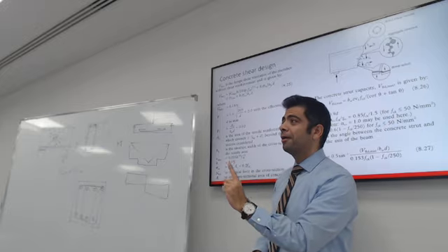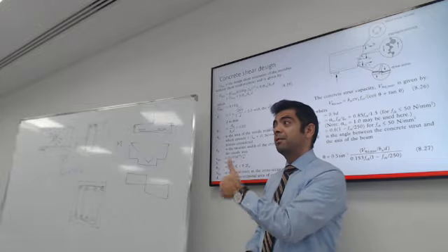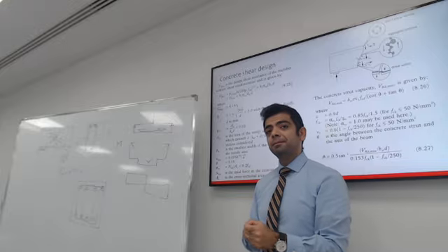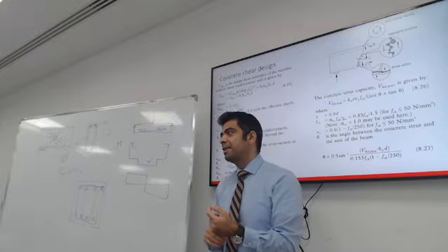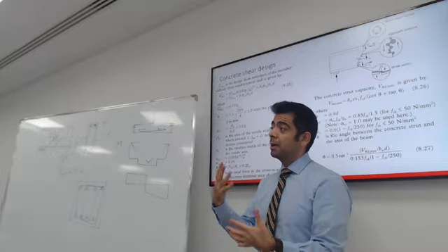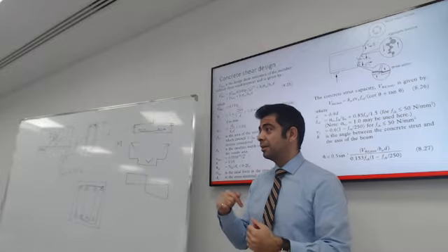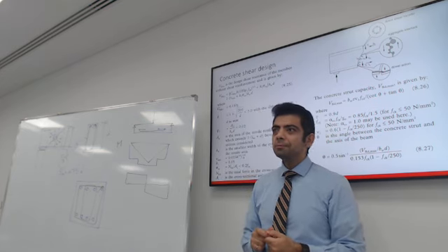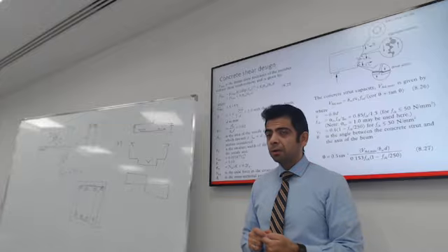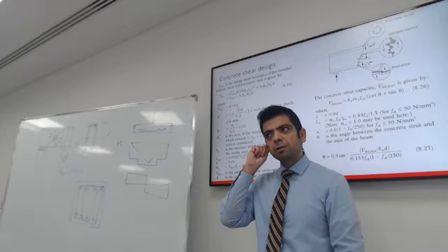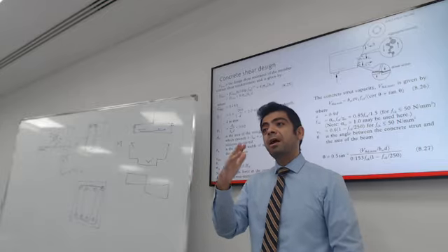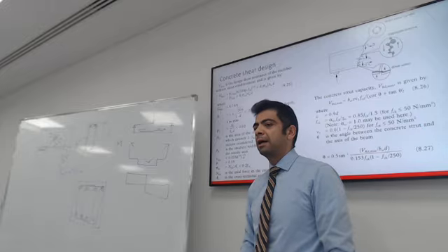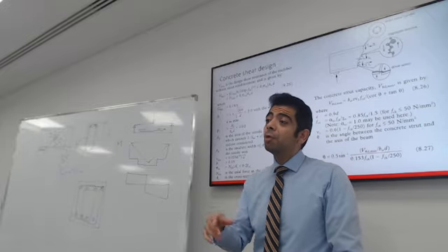There is one more element that could enhance or reduce the concrete shear strength. I'm curious if you can think of it. There is one more element that can increase the shear capacity for concrete or could decrease it. Could actually be a negative and be a source of a headache. Water. Water, especially if it has salts, could get into the cracks and cause corrosion, and this will damage everything. This will damage steel, and this will result in lower shear and moment capacity.